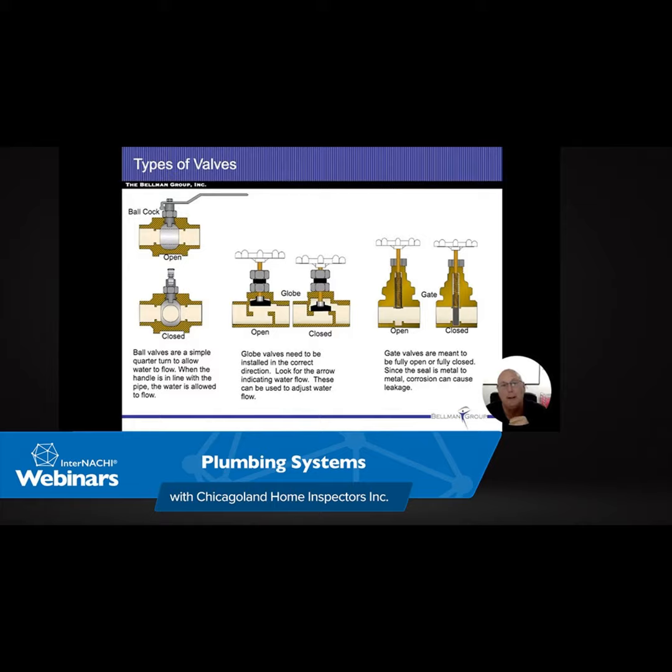And yeah, so it's 200 psi, 3/4 inch pipe on the PVC. And I do believe the CPVC is also 200 psi. They are both for drinking water. But I know the CPVC has a higher temperature rating than the PVC.